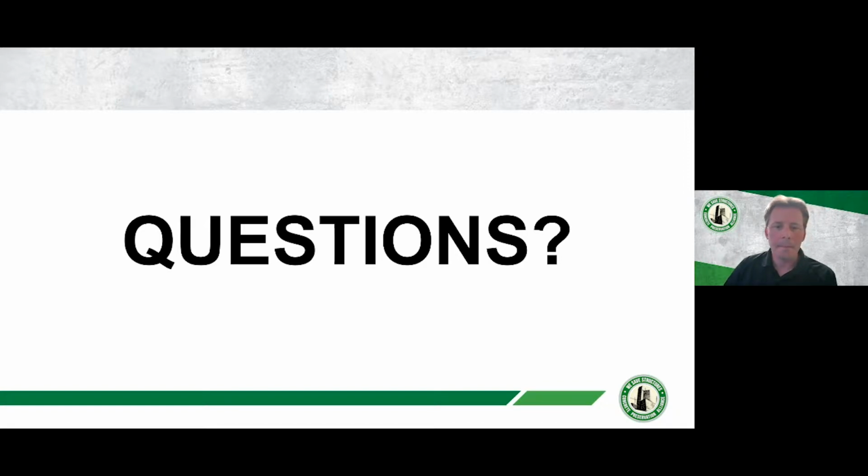Okay, the questions are flowing in. Another question from Sergey. I have to interpret this, but how dense of a grid pattern is required? I suspect he's referring to the zones. Zones are typically 1,000 to 1,500 square feet on your larger structures. When you get into pier caps and columns, we'll break them up and say maybe the pier cap is a zone or a structural element, and then we'll install our anode connection plates that way. And we like to have redundancy in our anode connection plates.